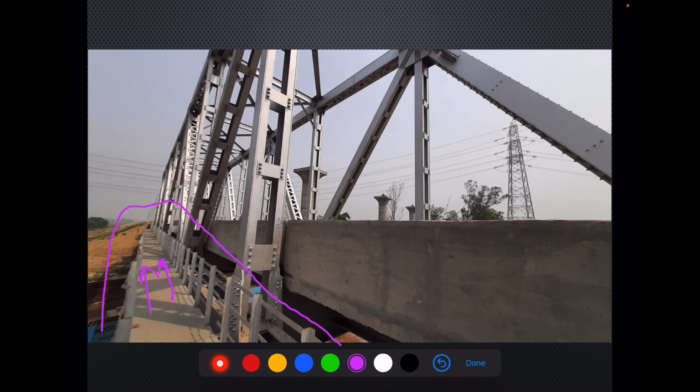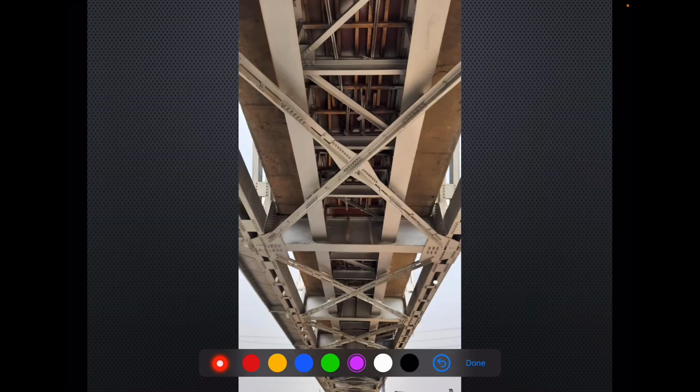They can inspect the health of the track also. So this is for that purpose, and this inspection platform is attached with the bottom chord. This is obviously the parapet of the deck, RCC deck, ballast deck. Yeah, this is important. This is basically the flooring system of the ballasted deck open web girder.